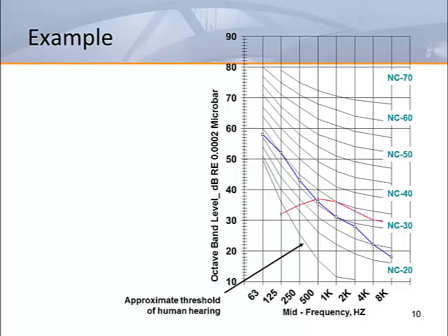If we moved to a location outside a mechanical closet and took a second set of sound pressure readings while the air handler is running, it would look like the blue plot. We would say that it's NC 35 and being set in the 125 Hz or 2nd octave band. You'll notice that instead of the ugly spike we saw in our fan-powered example, the air handler produces only a bump in the same band. Larger fans produce much smoother sound spectrums, but they still typically peak in the 125 Hz band.